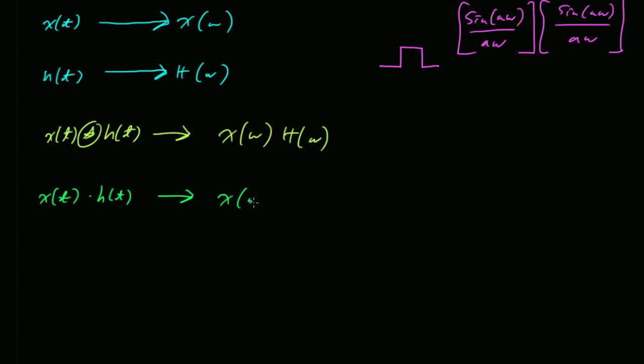And we saw that in the context of truncating a signal. If you take a signal, like a cosine, and you truncate it, that means you make it finite duration, then effectively you're multiplying that infinite cosine with a square wave. And in the frequency domain, that has the effect of convolving the Fourier transform of the cosine with the Fourier transform of the rectangle pulse.